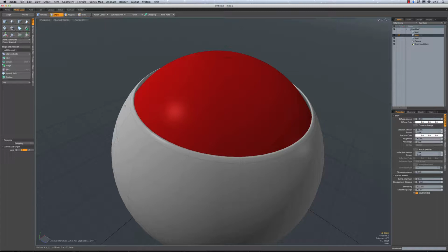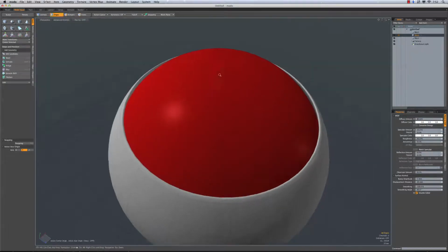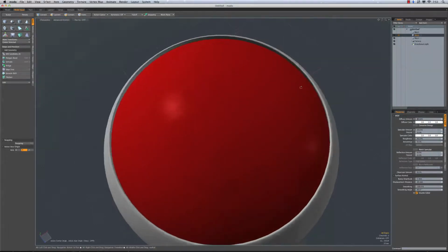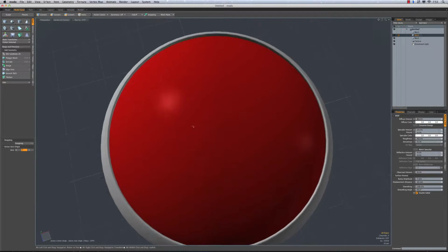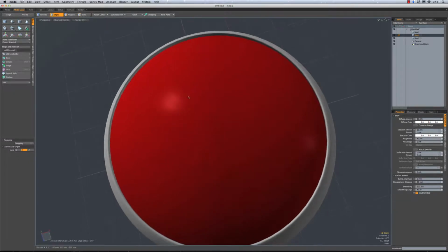So now we want to sharpen some of these rounded edges. And before we do that, there are a couple little minor housekeeping things that I like to look at mesh-wise with this model. And the first thing is the pole here, at least this visible pole. And having all of these triangles at the top kind of makes this a really lumpy mesh. So for one that I'm going to keep rounded here, I'm just going to go through and select every other edge and go ahead and delete those.